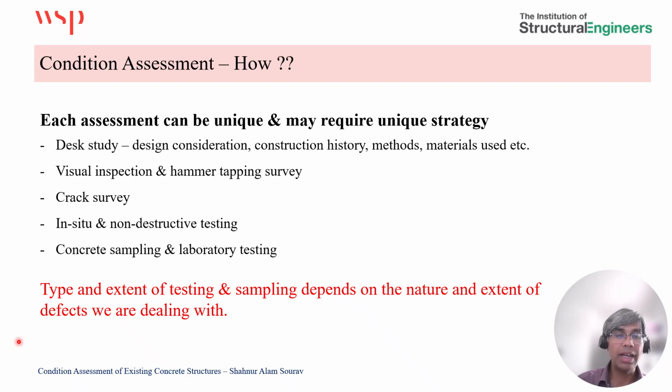Then we come up with a plan for how we can use in situ testing and non-destructive testing to inform what type of deterioration is occurring and what level of deterioration it is. We also sample concrete from the affected structures and elements for further laboratory testing. The type and extent of testing and sampling will depend on the nature and extent of the defects we are dealing with in those structures.